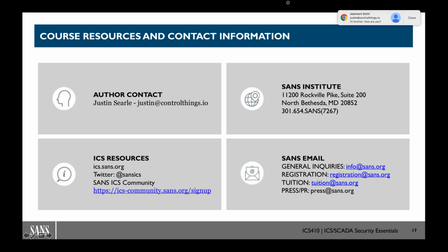And if we need to share resources between plants, say I have 5 plants and I'm sharing Active Directory between those plants, my recommendation is to build a VPN tunnel between those plants from level 3 to level 3 at each plant, and then allow Active Directory to share its traffic and its authentication or anything else through that level 3 network. So you still can have connectivity across the plants. We just want to make sure that it's securely done from level 3 to level 3 or demilitarized zone to demilitarized zone, so that we are not risking external compromise inside of the plants.